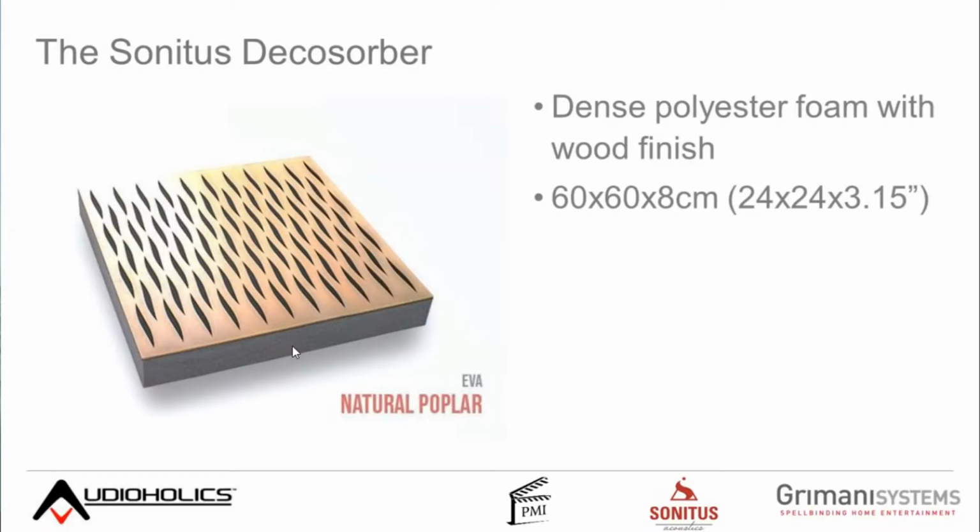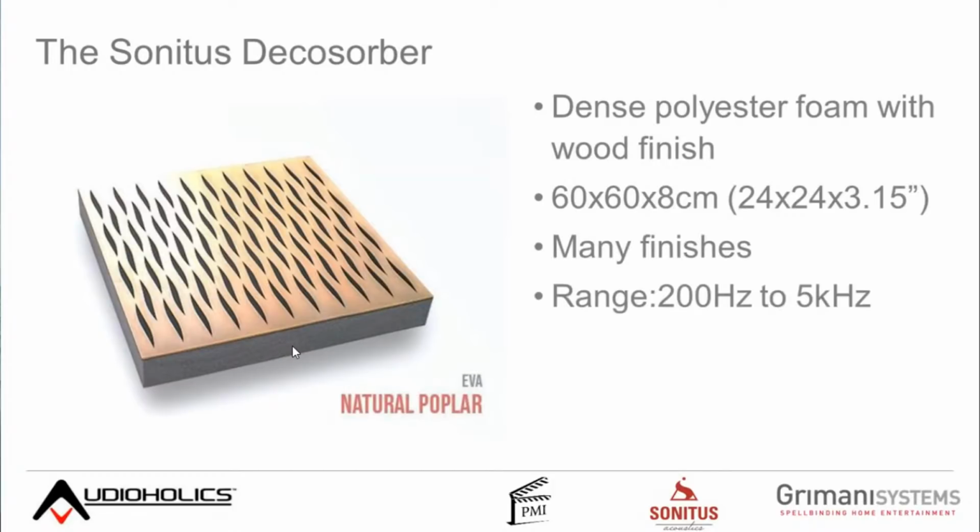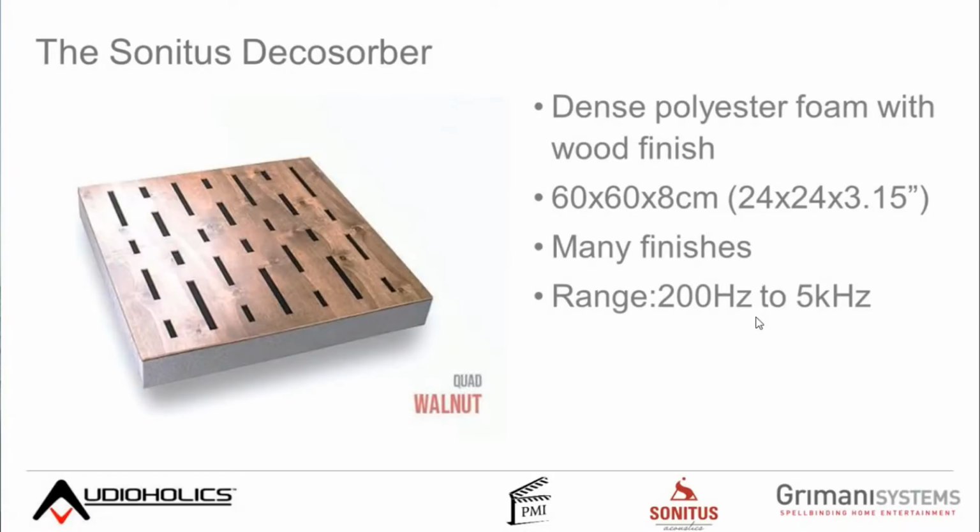This particular thing is 2 foot by 2 foot. It's available in many finishes, works over this range of frequency. You actually get a little extra kick at low frequency because the panel on the front acts as a membrane absorber, so you get a little bit more low frequency effect.